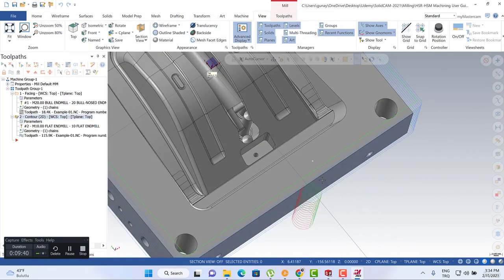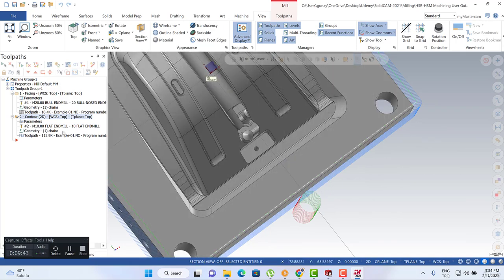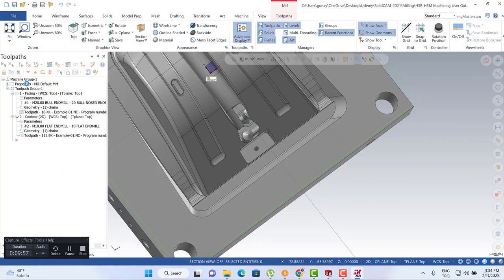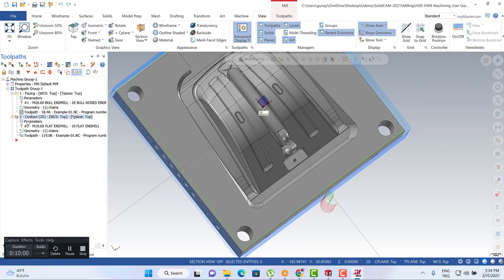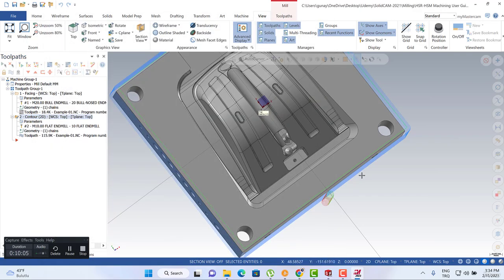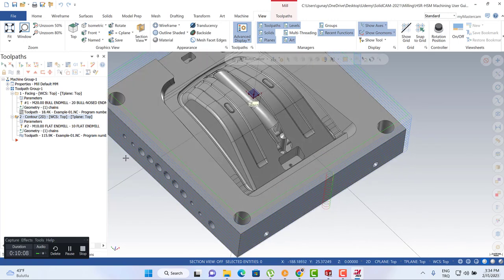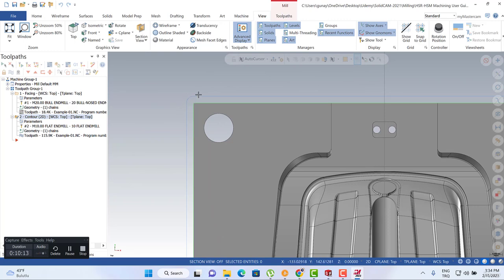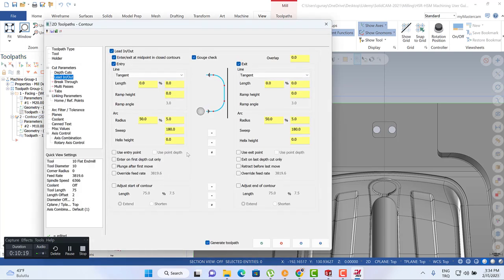Okay, and then we're going to see the toolpath here. Maybe we should also change the lead out and lead in arc radius by changing here. This is also a percent of my tool diameter. It is also calculated according to my tool diameter. Of course, we can also hit that button to make it the same as the other options. You can also see here, this is the rounding options. Of course, we're going to get sharp corners on the workpiece. That's all about the toolpath.